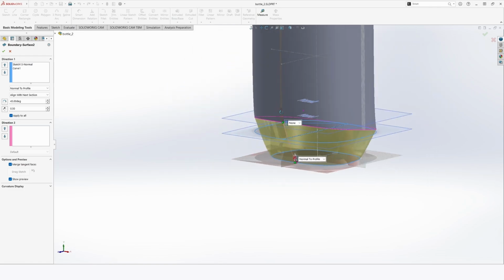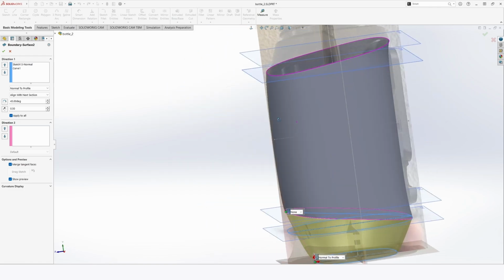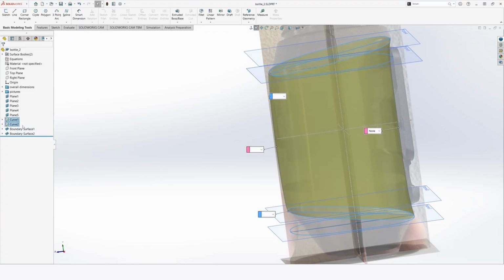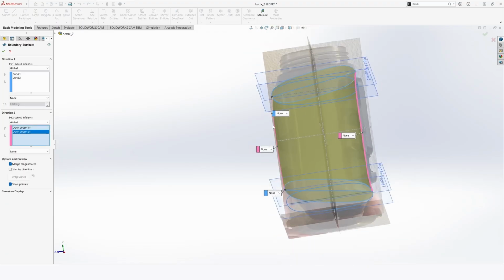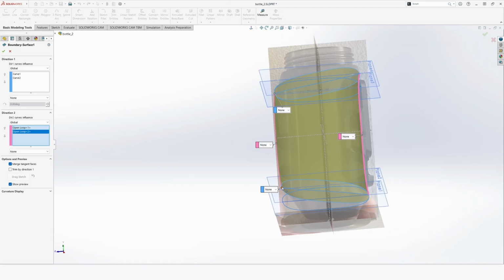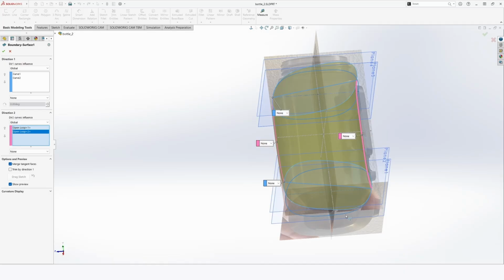And for example, if we had these guide-like curves from the first surface that we did, it allows a bit more control in this second direction. The first direction would be this closed surface to this closed surface, right? And then the second direction is how it wraps from this guide curve about the direction of my cursor here, right?